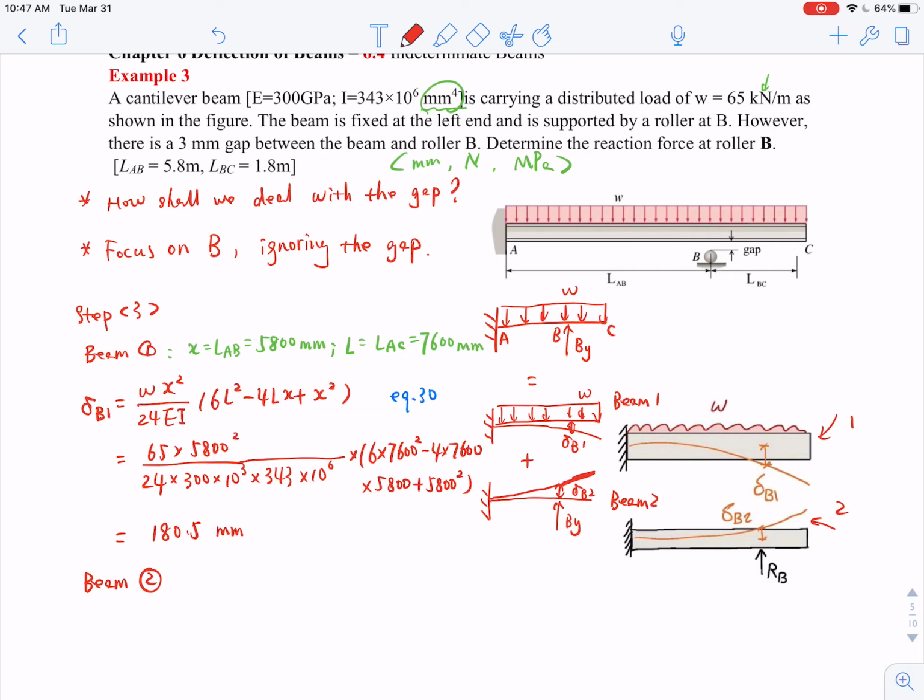This will not be bended. So if you're caring about the deflection at point C, you can use the triangle and the slope at point B to calculate an additional component. But here, since we're only calculating the deflection at point B, this section BC will be useless. We only calculate the part AB.